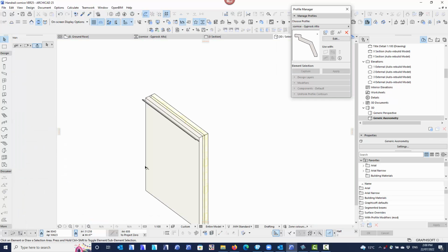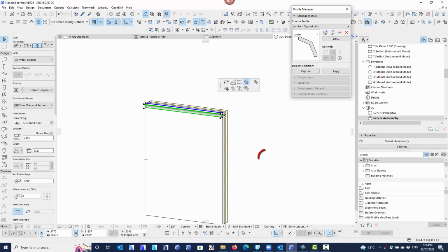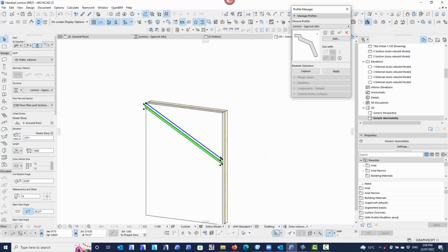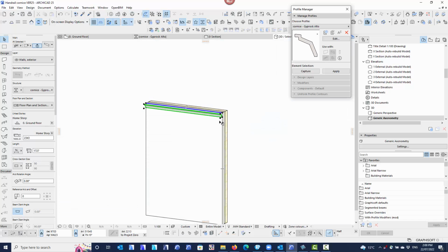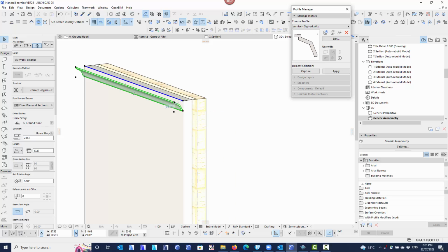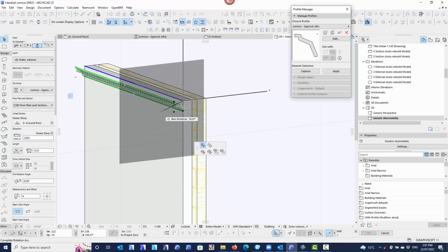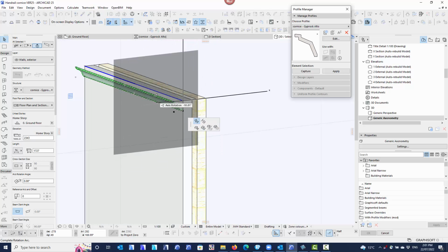The other thing you can do with beams, if we look at this in 3D, where I've got a little cornice just stuck on the edge of the wall there, being that it's a beam, I can take that beam and I can simply angle it. If I need to use that as a gable end or a raking ceiling, I can just simply choose either end and move them up and down. Also, if you click on a cornice, you can also rotate the cornice, so I can actually rotate that cornice to suit raking ceilings and things as well.